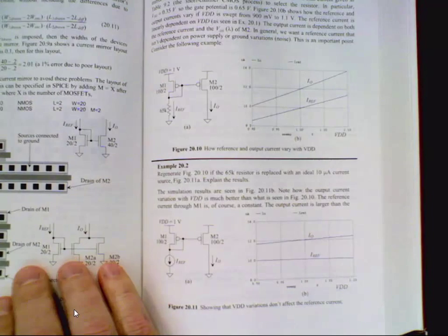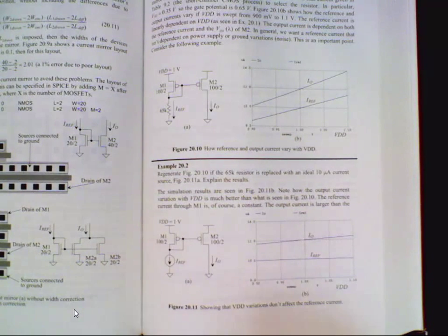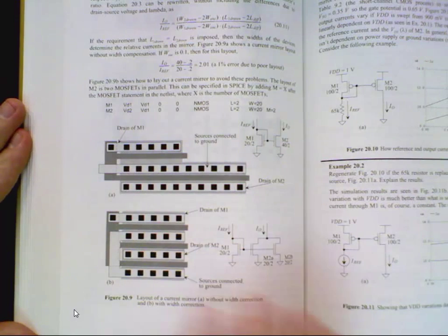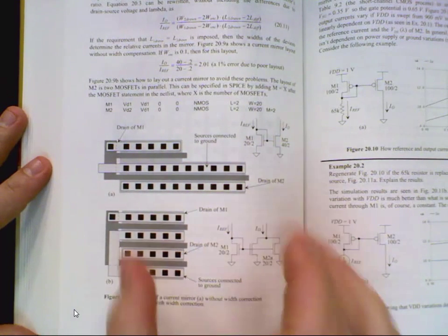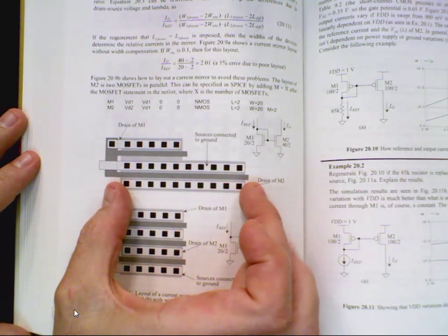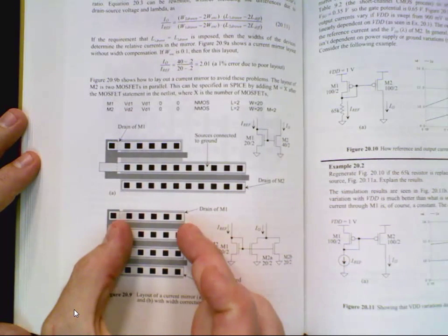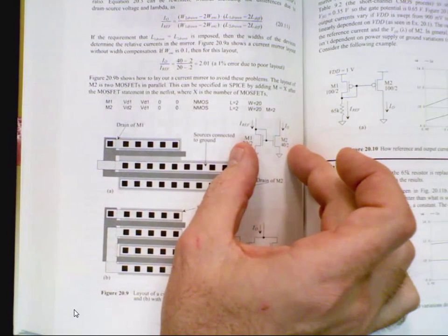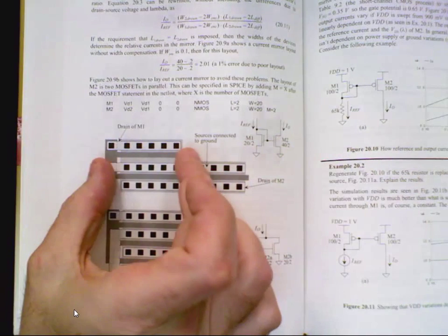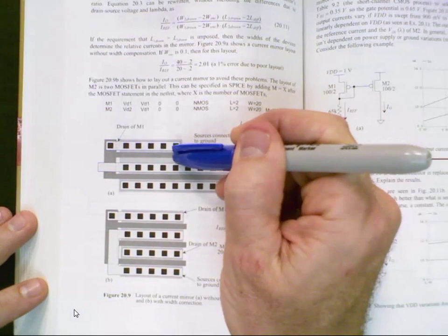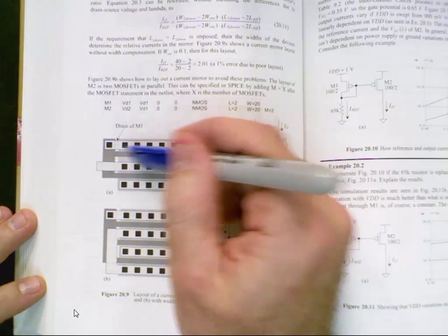On the next page, there's some discussion, which I'll talk about in 2 seconds, on common centroid. The other thing you want to do, and I talked about this earlier, you see how this transistor, say, is 20 by 1? And this one is 10 by 1, just as an example. Or I guess it's 20 by 2 and 40 by 2. But you see that there's a little bit of encroachment on these two edges on the width.